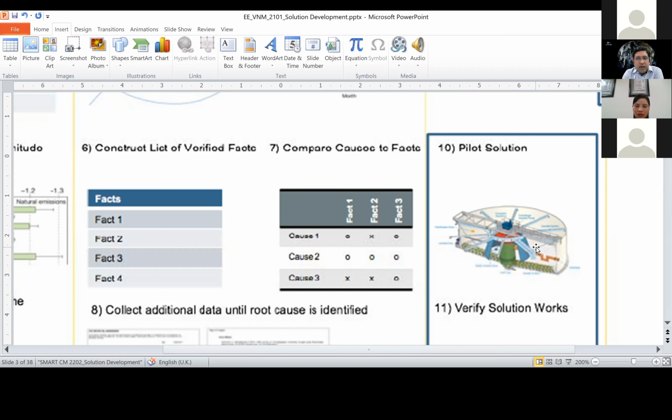So once you have done anything, always look for standardizing it. This 5S is actually 5 Japanese words, where the first S is seiri, that means sorting. So you sort whatever you have into good things or bad things, needed things or not needed things, for example, and then you keep only those things which are needed, and then you clean everything, you put everything in order, and then you standardize it. Standardization means that whatever problems we were having, these must not occur again.